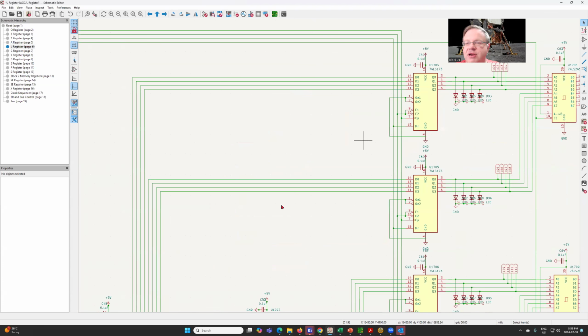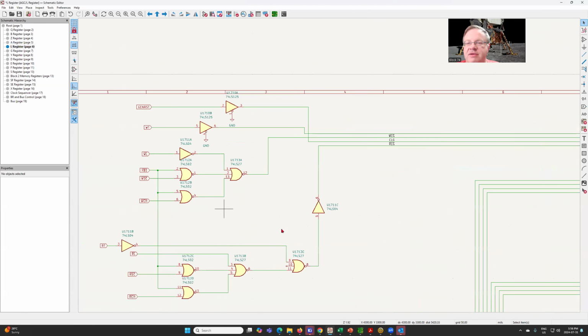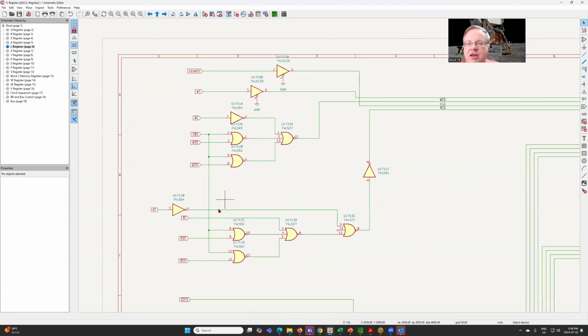So these are our registers right here. And then we have the write logic to determine when we push data out onto the bus. Again, similar logic: we have the RL pulse, the RSC, and the RCH, and these two are also combined with XB1. Now, the one nice thing about the L register is that going through some of those control pulse combinations that we talked about in the last episode that can result in bus contention, there is none that the L register has to deal with.